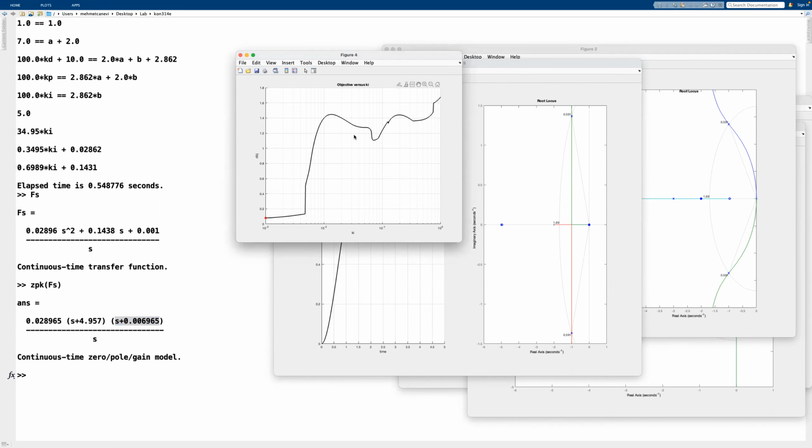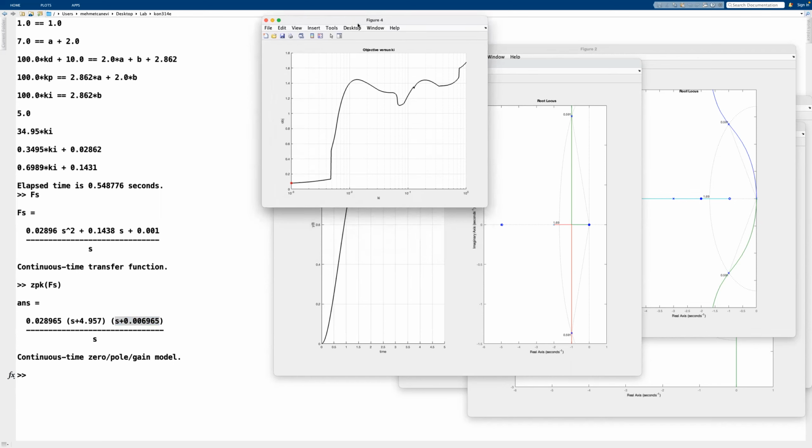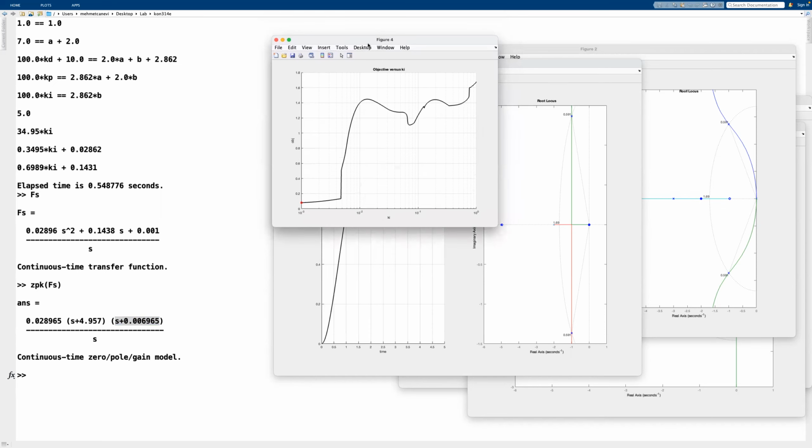And you can see here are some different behaviors going on, but from this point on, we're basically tending to the optimal solution, which looks like global optimal, by the way. And it is. Yeah, and we've shown this numerically. So this is a very special example, therefore, to showcase to you that sometimes pole zero cancellation can give you the best answer. But if that's not the case, this numerical one would come up with a solution that would have the best step info results like settling time and overshoot.